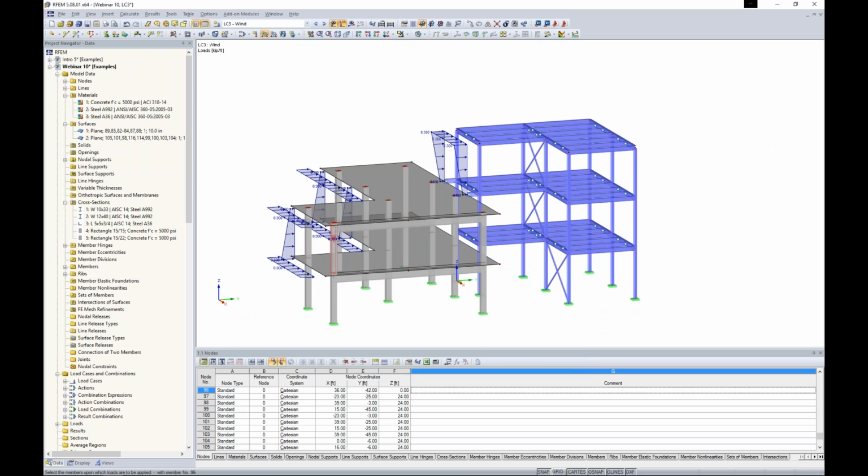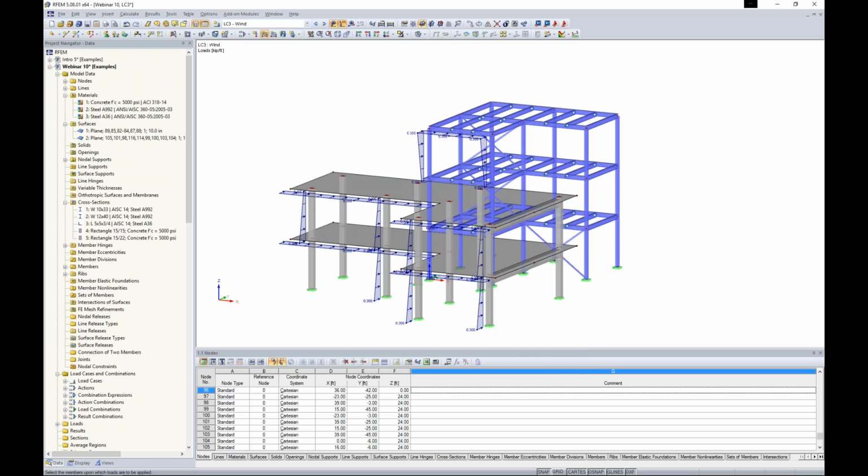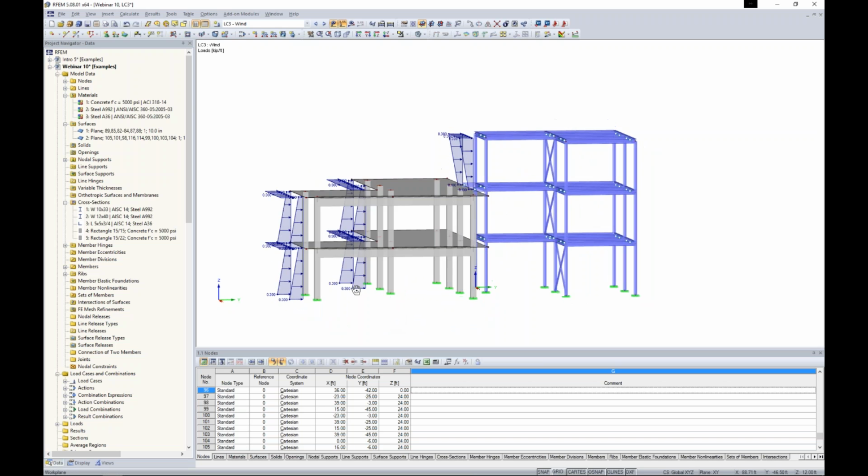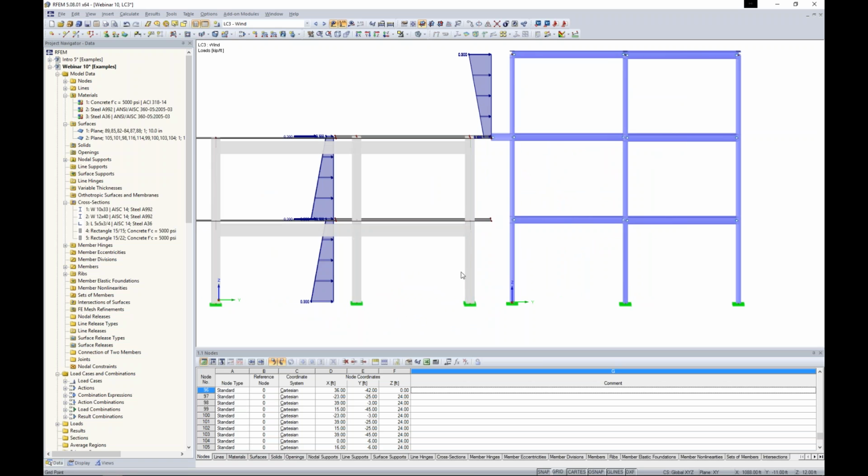Now you'll notice as I'm clicking on these members that typically with wind loads, I would like to apply a higher magnitude at the top and lower magnitude at the bottom. Well, that's fine for over here, but it looks like our concrete members are opposite. So I could easily double click on these member loads and switch them around, but you'll notice that my columns start by the big red arrow here at the top and finish down at the bottom, whereas my steel are opposite of this.